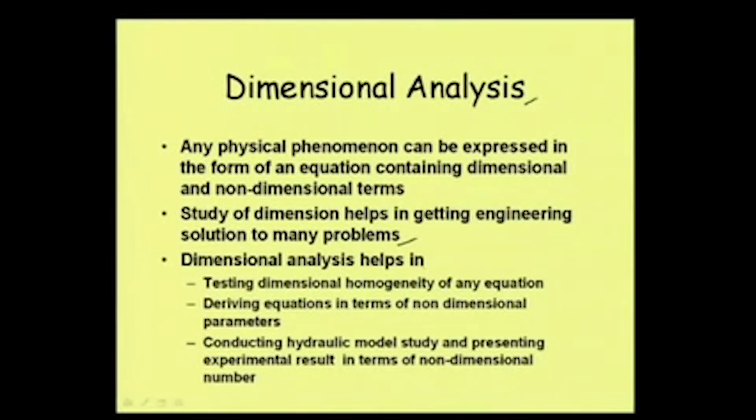Dimensional analysis helps in testing the dimensional homogeneity of any equation. So, what do we mean by dimensional homogeneity? In an equation we will have a left hand side and a right hand side. If we write the dimension of the left hand side, say if it is Q, discharge, then it will have some dimension, or suppose we are talking about depth. Depth dimension is nothing but L, length.